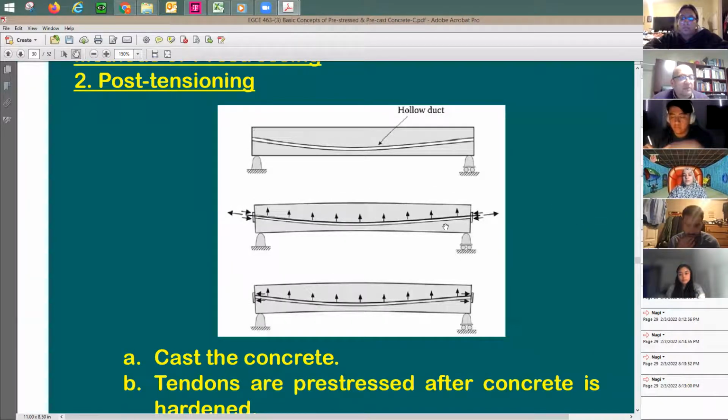And then once you start to do this, now you have this tension on the beam, right? At this side, it means that you're lifting up the beam. This is exactly what you're doing. Once you start here to apply tension, this strand here wants to stay straight. It wants to do this. You see here what's happening? It wants to stay straight. So it is pushing up the beam, which means it counteracts the effect of the conventional loading that later on you're going to be putting on the beam from the top. So you're going to give it here more service life, if you like, or give it more service capacity.